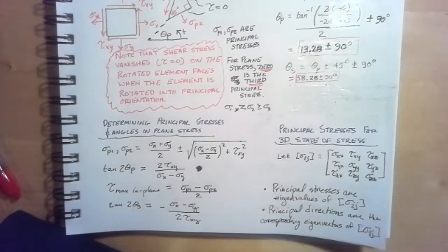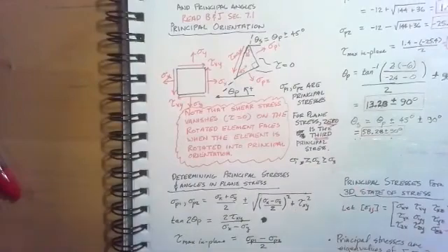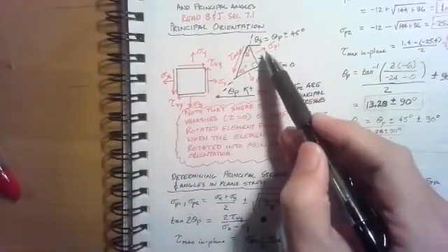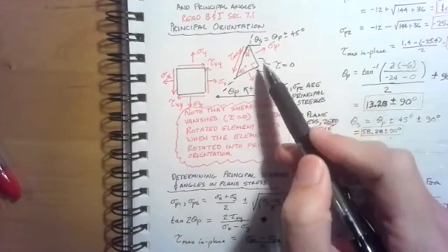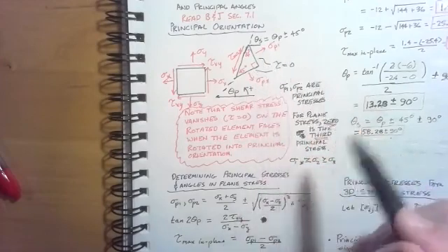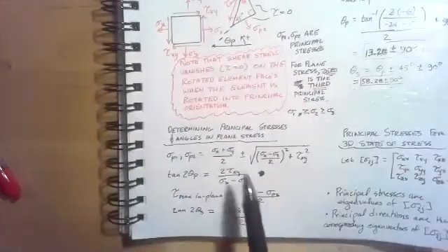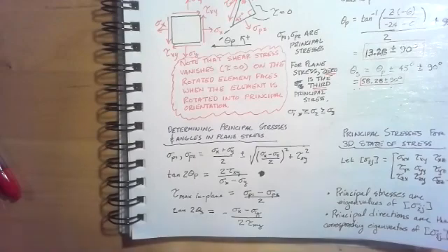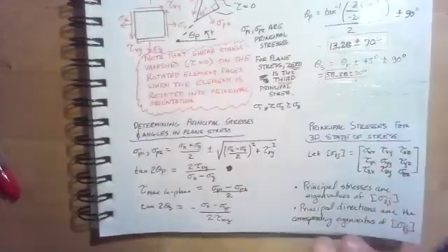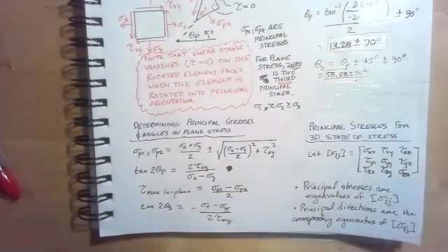But it's pretty easy to get the principal stresses. So at the end of the day, the thing that you really need to remember from this lesson is that principal stresses are the stresses where the shear stresses go away. And we have ways to calculate those for any state of stress in plane stress. And if it's a 3D problem, we would just be doing eigenanalysis. That's it for video lesson 18.